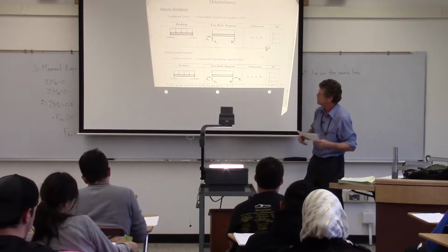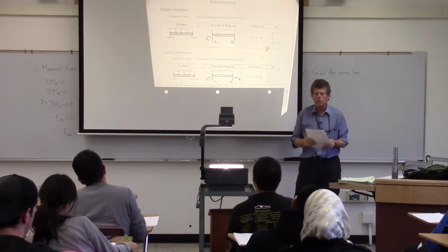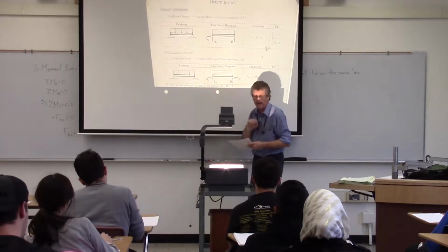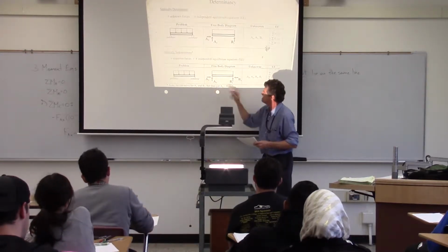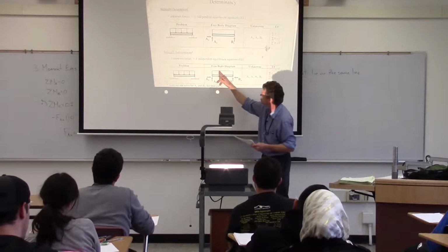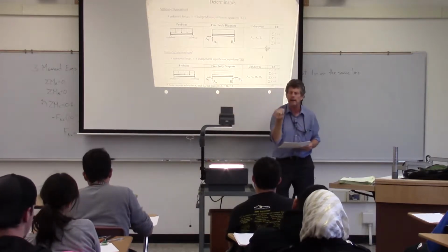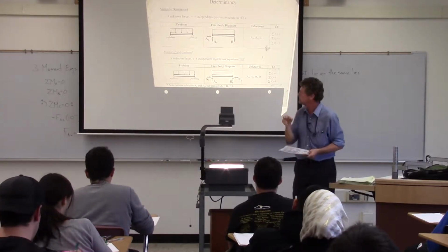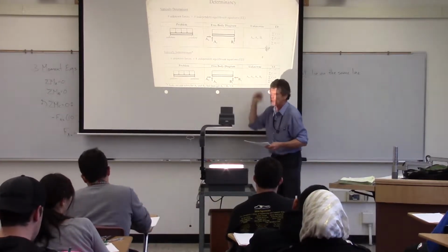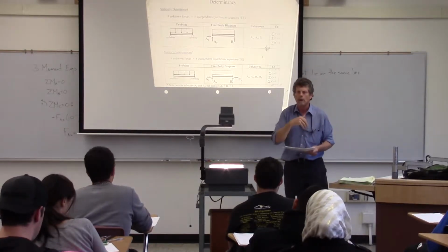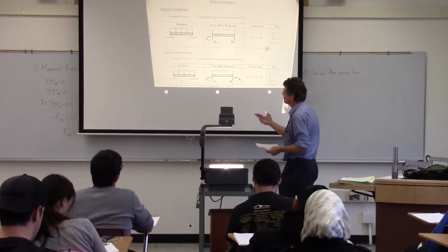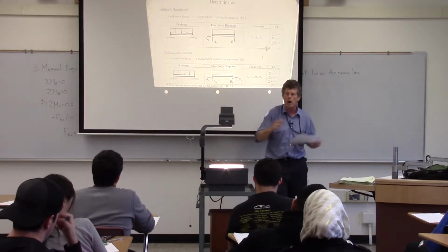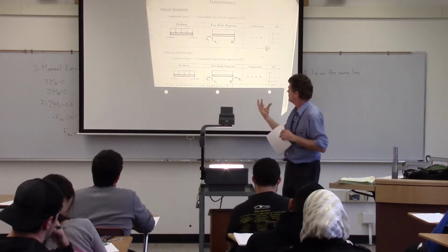But there's a little note there, but note we can solve for some stuff. If we think about it, if I were to take a moment at the A point there, this is some sort of a loading. We'll get to learn how to do that later. But note that at A, the AX and the AY do not participate in that equation, right? Because they go through that point. But also note that BX, since it happens to be in that same line there, also does not participate in that moment equation. So I can write a moment equation that includes this load and then an unknown BY in some distance. So I can solve for that, and I can do the same thing.